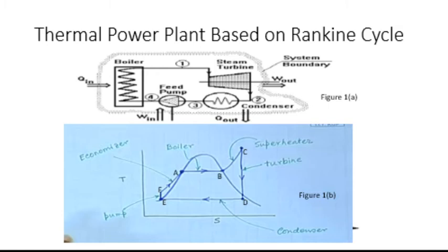From 2 to 3 you will say, if we are condensing it, changing its heat, cooling it down, how is the pressure not changing? Because the heat we are taking out from the condenser is only the latent heat. As latent heat has been taken out, there will be no change in the pressure, because pressure depends on the temperature. If temperature changes, pressure will change.